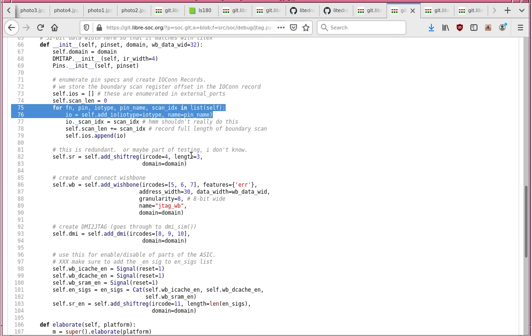You know, the FPGA's I/O is assumed to be reliable. It was tested at the factory. Whereas here, you can't get away with that. So this is another reason I think you have to have a boundary scan check on an ASIC, because otherwise you don't know which bit is broken: the I/O pad itself, or the peripheral connectivity driving that I/O pad.